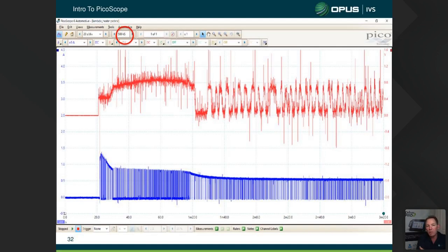So what we can actually do is reduce the number of samples per second we take. We just hit this little down arrow here and we drop that down as far as we go when we do an oxygen sensor. And that'll clean up our pattern a hell of a lot. It gets rid of all this interference that comes in from injectors and alternators turning and all that stuff. All these little spikes is interference. The scope picks up absolutely everything.